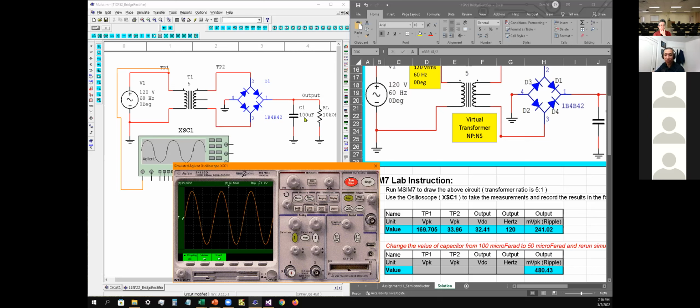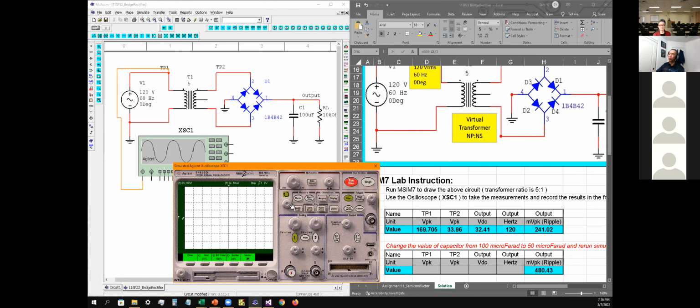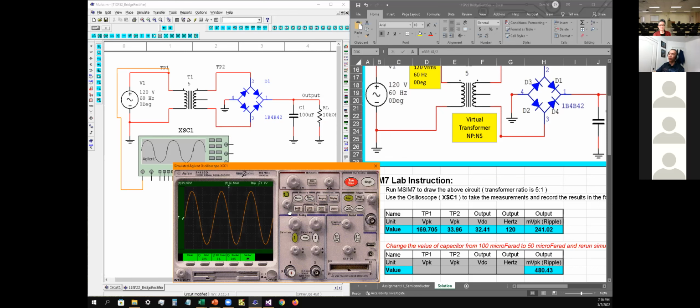Quickly, how do you go from a black background to a white background? Okay, so you click on the display button here. And then you have this one that says clear grid, black, BK color, that represents your background. So you click on that and then adjust it with this adjust button right here. So you can adjust it to very bright, or you can use a darker background. Okay, got it, got it.